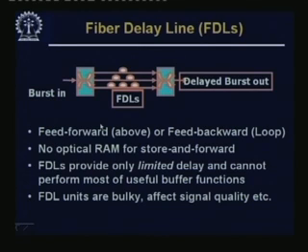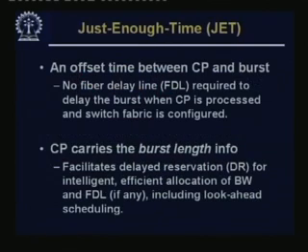Fiber delay lines, I just mentioned them. These can be feed forward or feed backward. There is no optical RAM for store and forward. An FDL provides only limited delay and cannot perform most useful buffer functions. FDL units are bulky, affect signal quality, etc.